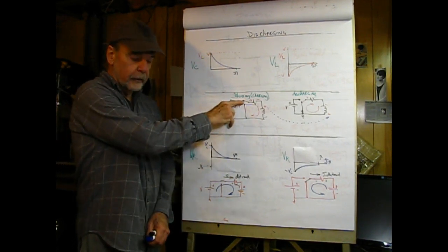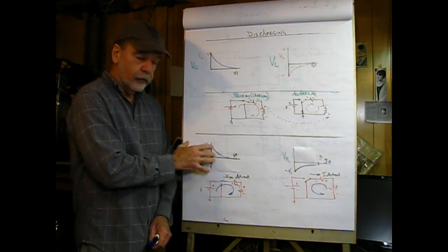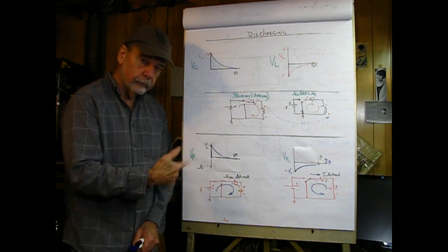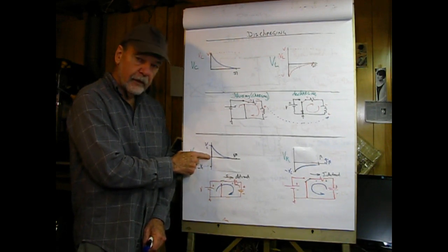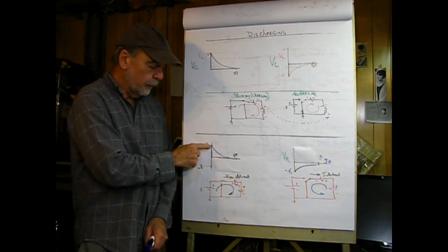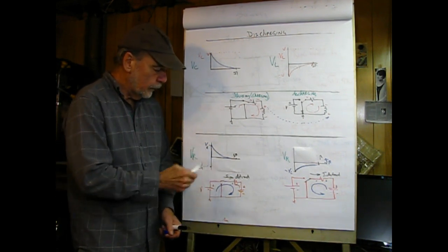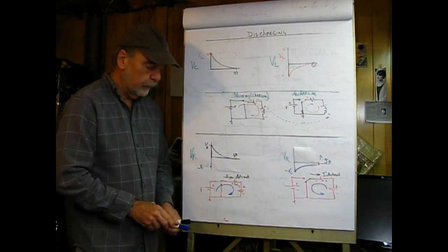Taking a look at the voltage across the resistor when a capacitor is charging, that would be when the switch is in this position, in the capacitor circuit, the voltage across the capacitor from last time would be equal to 0 volts, and hence the voltage at T equals 0 plus would jump up to the supply voltage. Let me get rid of this here. And then it exponentially decays as the capacitor becomes charged.